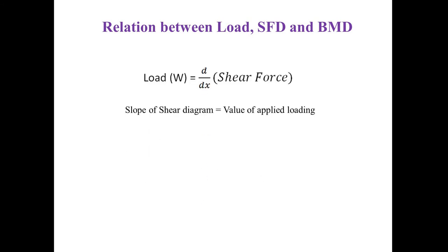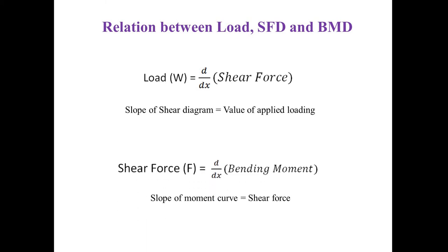Now we'll see the relation between the load, SFD and the BMD. The load is equal to d by dx of shear force. If you take the load W, that will be equal to the differential of shear force. So the slope of the shear force diagram will be equal to the applied loading. Then the shear force will be equal to the differential of bending moment, d by dx of bending moment. So the slope of the moment curve is equal to the shear force.